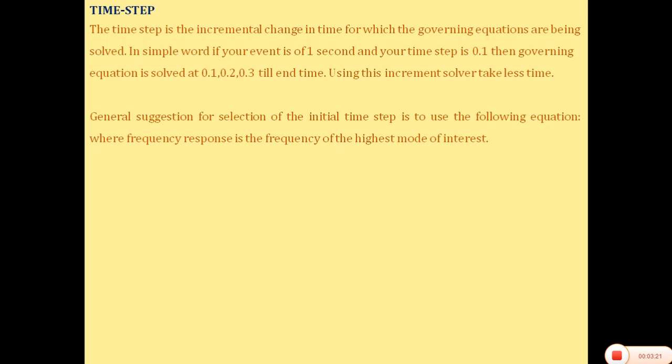If I give a time step of 0.1, then the solver gives me the answer at 0.1, 0.2, 0.3, till the end of time, till I get 1 second. This is a time increment, a time integration thing, due to which the solver solves this problem very fast and gives us a result.